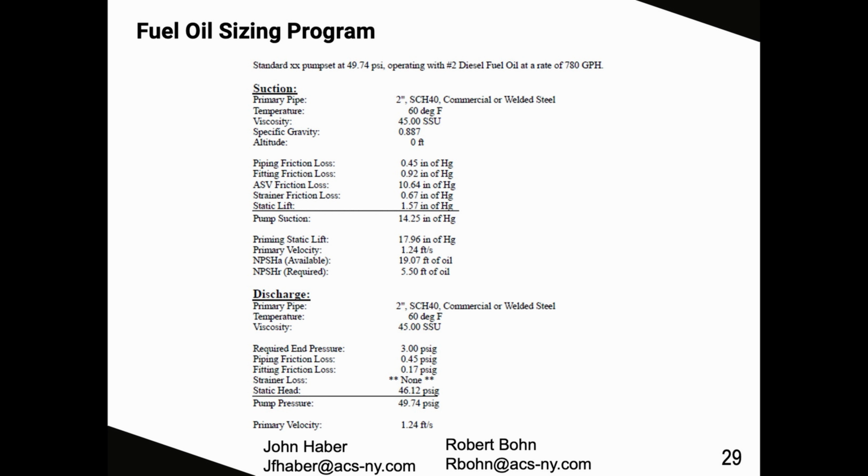We also went with a 2-inch discharge line. We also, again, are able to show you your velocity for your discharge, along with the pump pressure, and that is going to be the back pressure pushing back on your pump at the discharge line. So depending on how many floors you go up, you have all that head of oil pushing back down onto your pump. This is again very important when sizing.